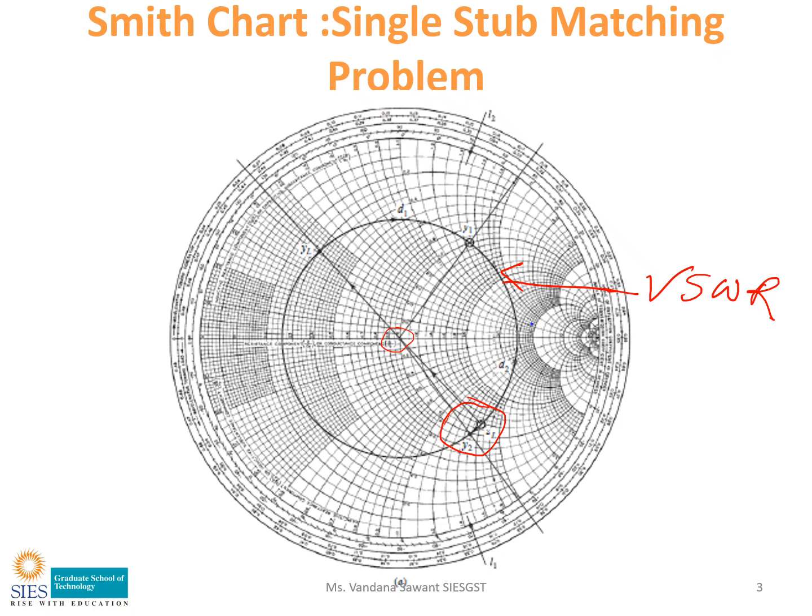Now your YL point will be on this circle exactly opposite to ZL. So we draw a line from the center at 180 degrees from ZL, and that line will intersect the circle, and that point is YL.